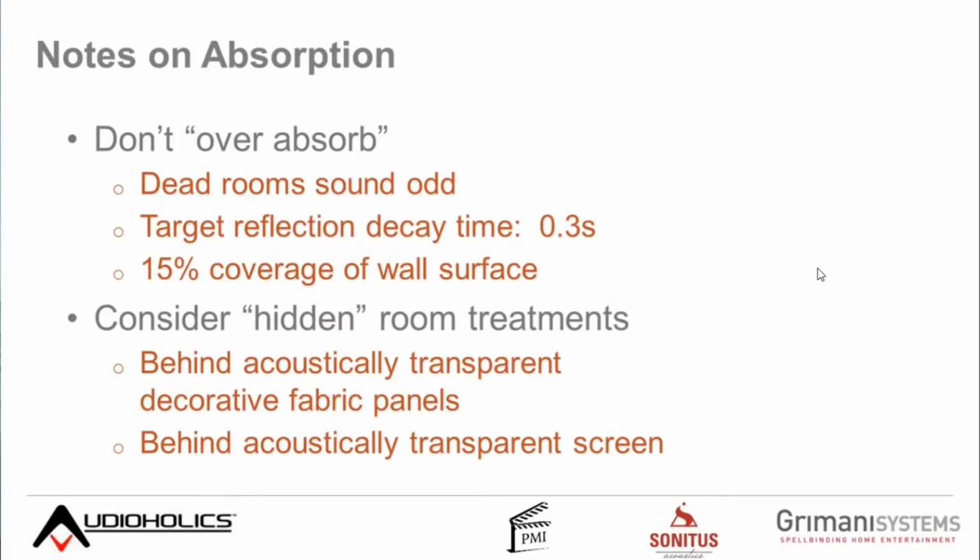Well, they don't have to be visible. You can do a stretch fabric wall. So that same thing I showed you before with the track, where's my piece of track here? Forget it. But you can actually put some absorbers on the wall, maybe 4-inch thick. You can put some furring strips to build out about 3.5 or 4 inches. You can put those tracks on the wall and stretch fabric to cover the absorbers. And if you're going to do that, make sure the fabric is acoustically transparent.